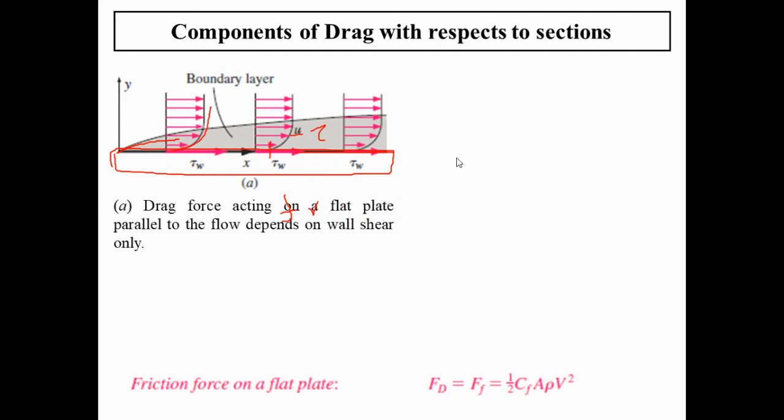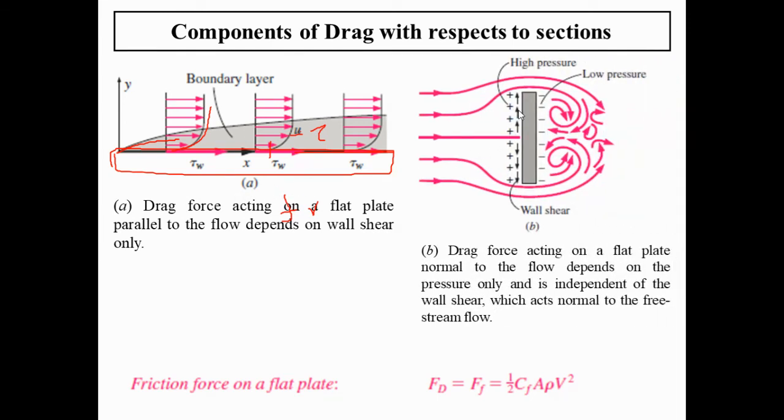We can also say that if the plate is kept vertical, you find less area in contact with the flow. So the flow gets separated here, and this is the wake region. This is a low pressure region indicated in negative signs, which we also call the suction pressure. On this side it is going to be a positive or high pressure. The flow will tend to go like this, and most of the pressure is here; this point is a stagnation point. And here is wall shear.